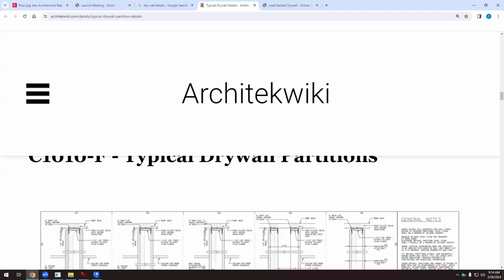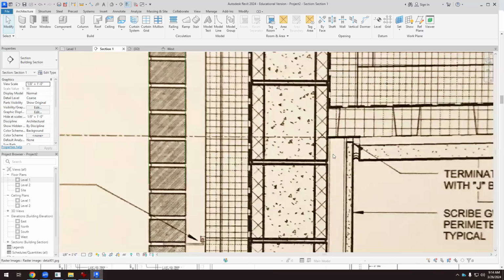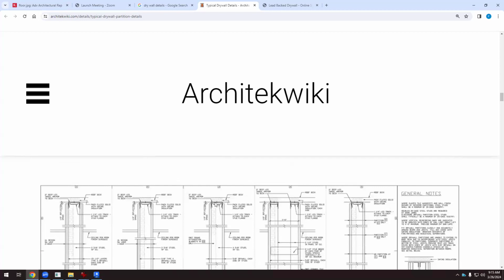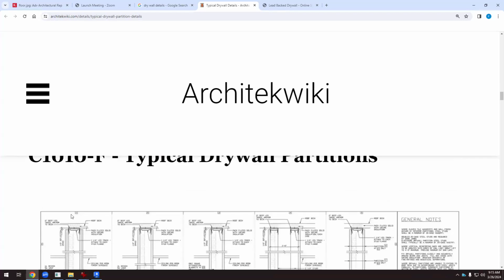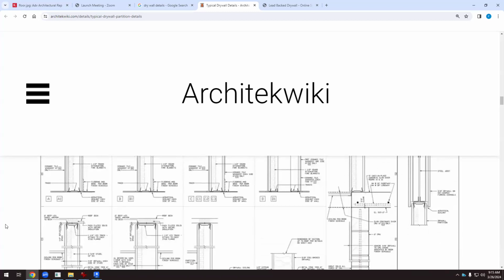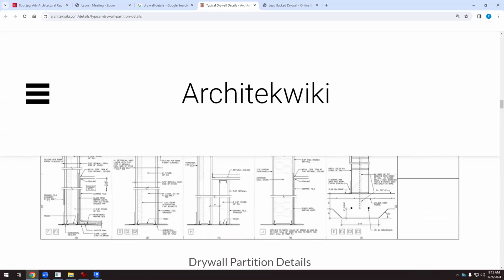This is the facade. So in the facade, apparently they haven't done it. Okay, so they haven't filled this, but these two lines that we have here are the projection of this element, this aluminum profile that we have holding the drywall. Then if we want more protection, we can have a double drywall like this one or a single one, depends. But this is what the drywall detail is.